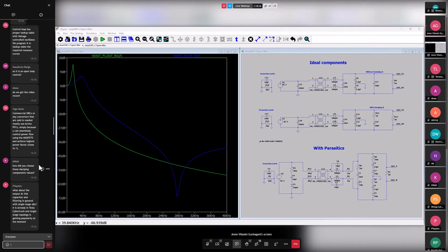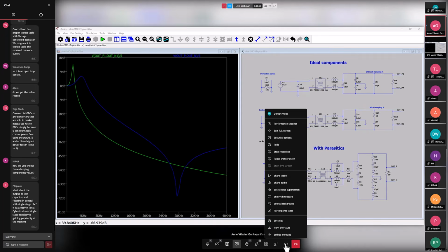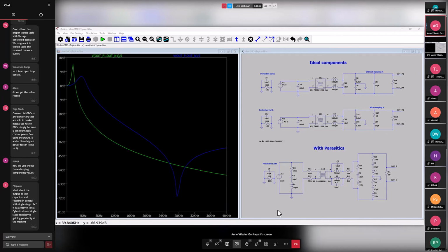To summarize what we spoke about so far, the onboard charger is the vehicle's only AC to battery path. When you do DC charging, it goes directly to the battery, bypassing the onboard charger. The passive components are important because roughly 40% of the volume inside an OBC is passives, and 30% of cost also comes from these.